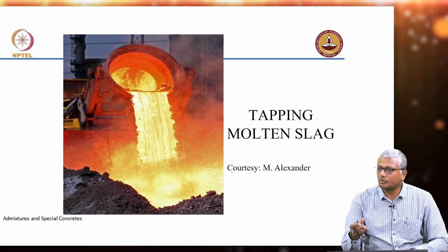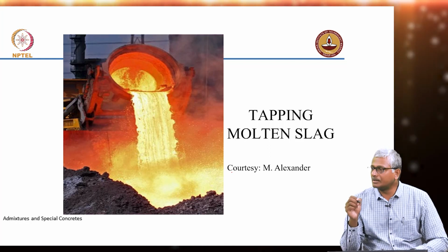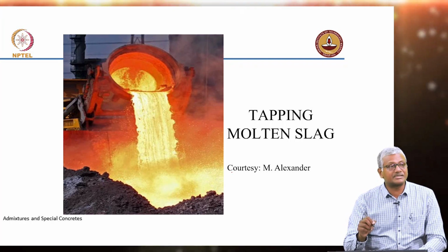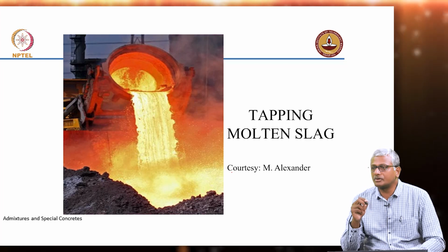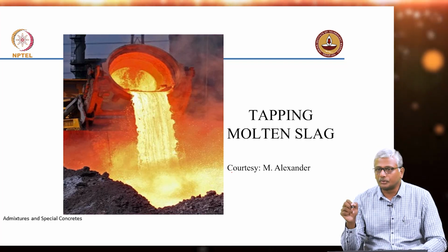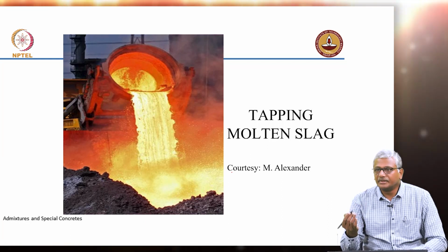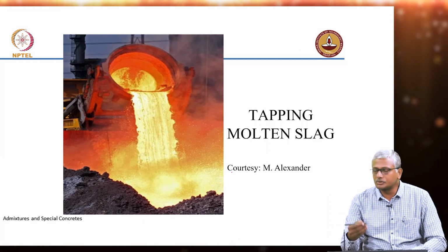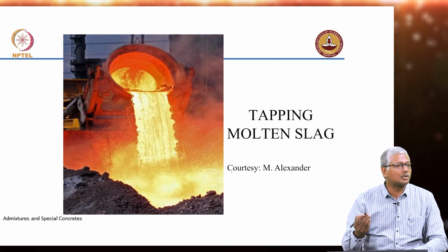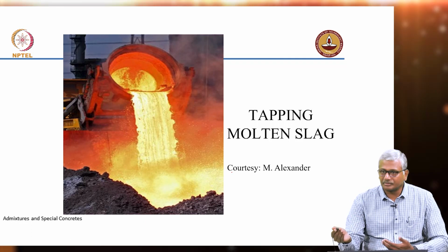So, there are different ways of cooling, but to produce a concrete or produce a material that is highly amorphous, what methodology should you choose? Cool fast or cool slow? We need to cool very fast in order to make the material amorphous. If you cool slowly, just remember same thing with your molten magma, which makes your rocks.